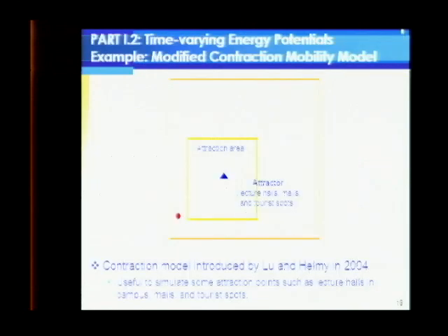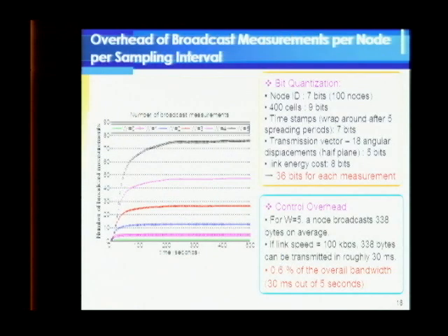So somehow that we call angular displacement, position information. Yeah, so when I'm making link cost measurements, I record the energy that is consumed to the next neighbor, as well as the direction of the arrow where that neighbor was located. Because then when a node takes the average of that cell, it averages not only the link cost, energy link cost, but also the displacement vectors, so that it lines up towards the base station. So I need to be able to angularly quantize these things and encode it. That's why I put in 5 bits there.